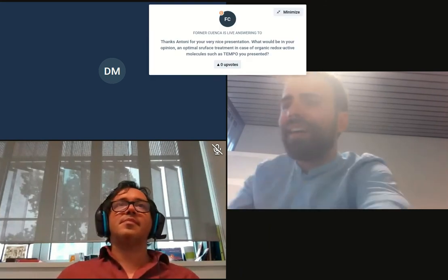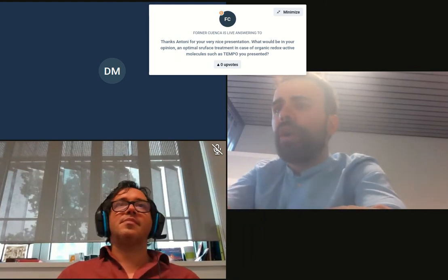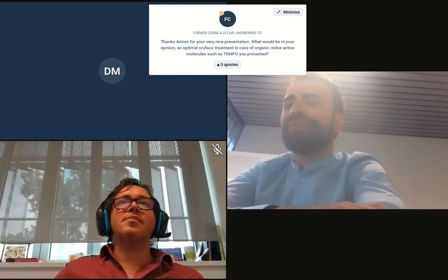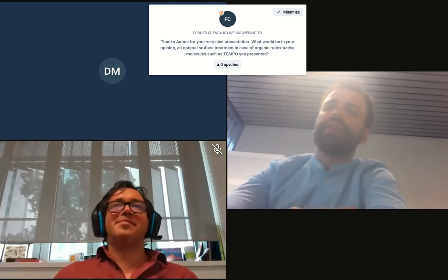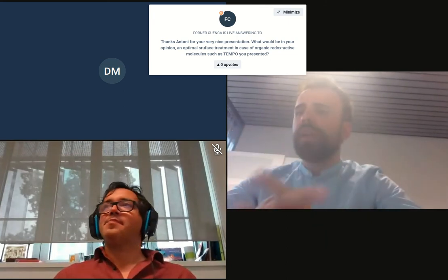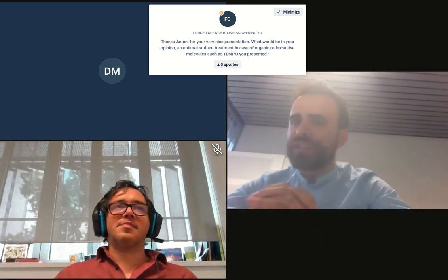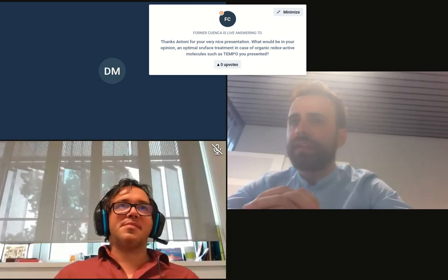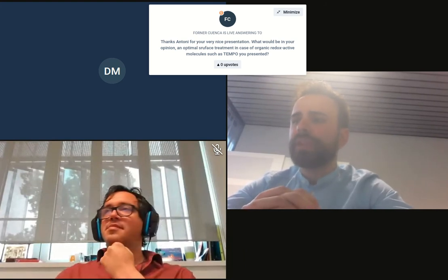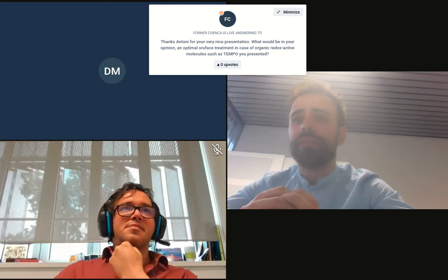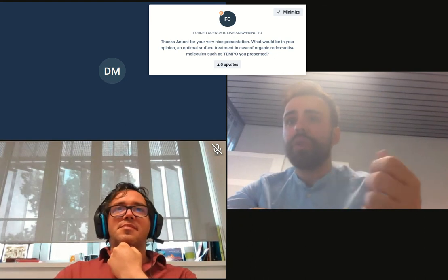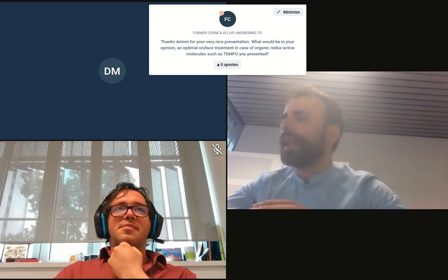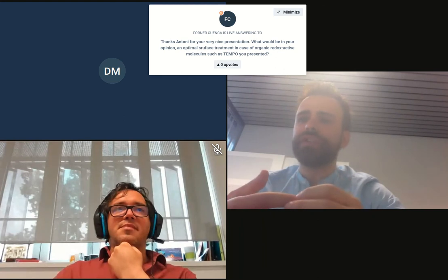Hey, thanks. What would be, in your opinion, an optimal surface treatment in case of organic redox active molecules such as TEMPO? That is a great question that I asked myself. Let me tell you something. I think, in principle, you might not need a sophisticated pre-treatment for organic flow batteries. The reason is that the organic electrolytes wet very well. Their surface tension is very low as compared to water, and because the surface tension is so low, you have full wetting, yeah? And so you are utilizing your area much better than in an aqueous flow battery.